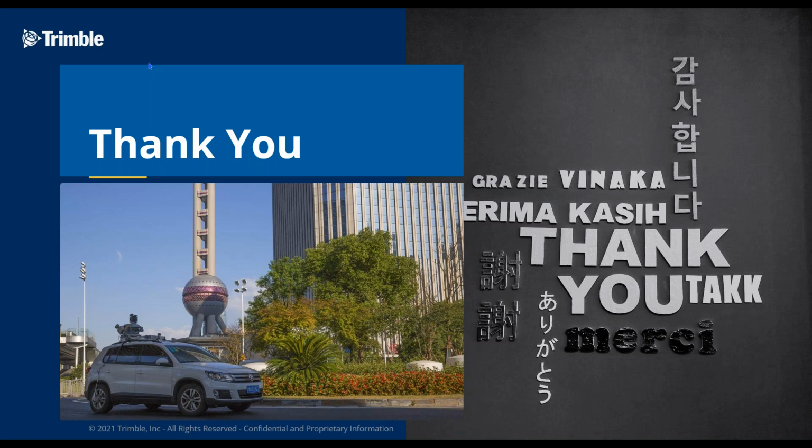I think that will be possible in TBC, which has some tools to reduce the point cloud density. In TMX, we don't have such a tool to reduce the point cloud, other than classifying it or defining it as a terrestrial data set or mobile mapping data set. So there are some threshold values already defined there, but in TBC for sure that could be done.